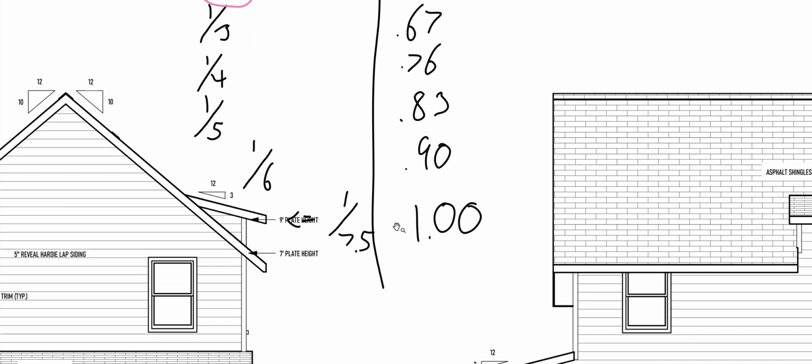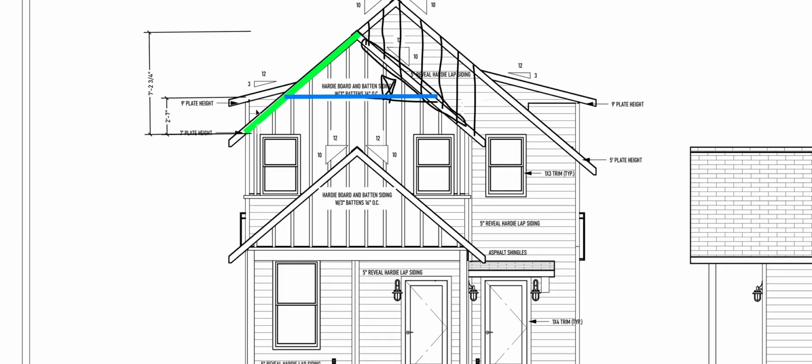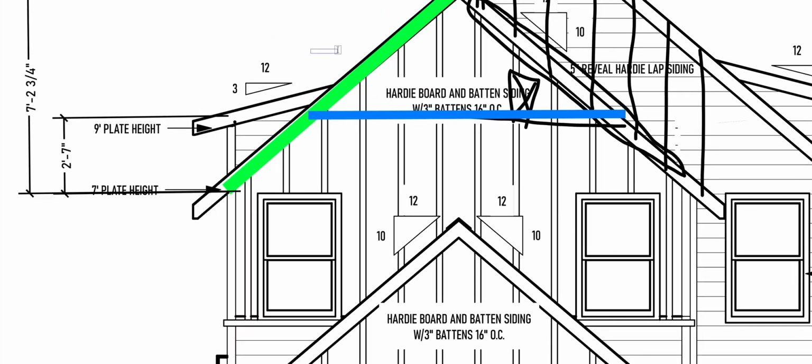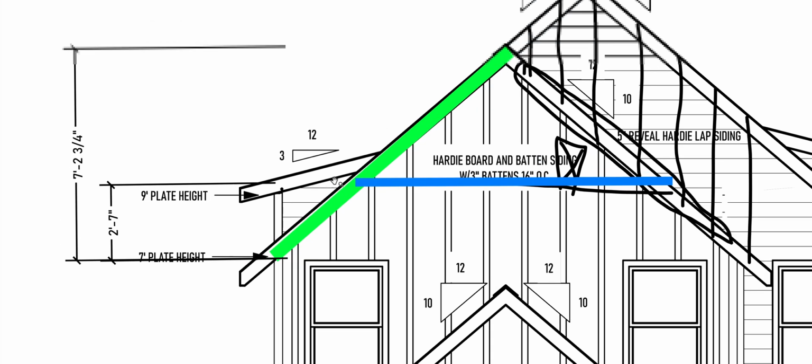This is a less than or equal to sign, and basically it's saying when that ratio is smaller than 1 over 7.5, it makes essentially no difference. Even though I'm raising my ceiling joist up a little bit and it's not sitting on the wall, putting the weight on the rafter, if this ratio is smaller than 1/7.5, it doesn't matter. It's not going to affect the rafter.